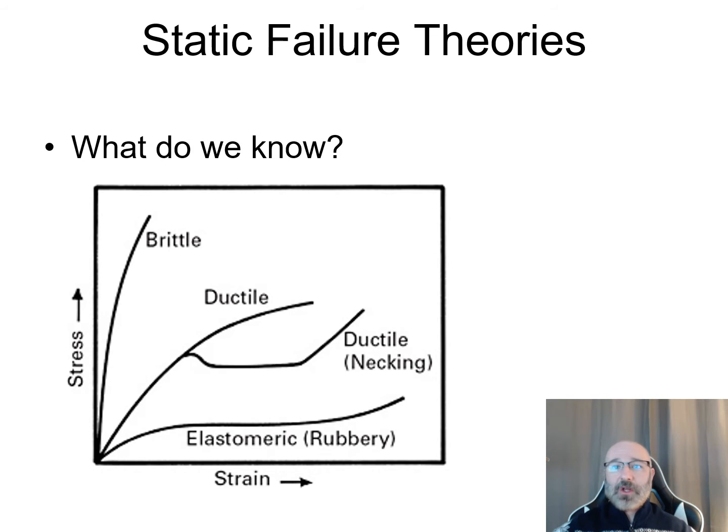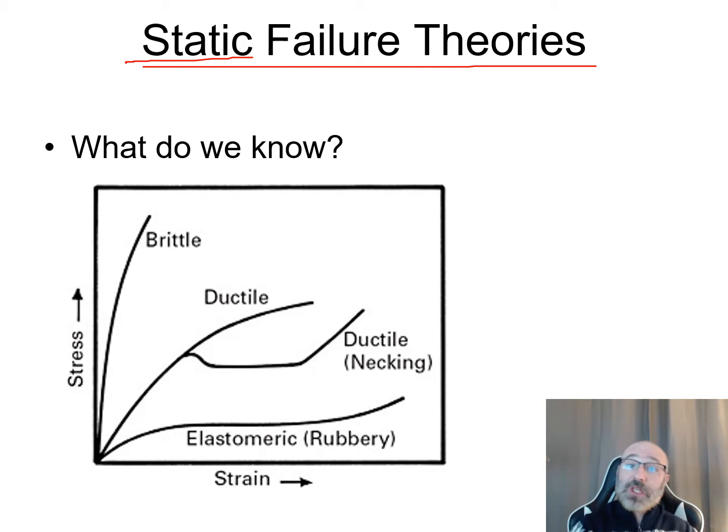So as we mentioned earlier, a lot of the loading we're dealing with within this module here and within this course right here for that matter is going to be dealing with our static loading right there. So with our static loading, let's take a look at some of the static failure theories. Now, a great resource for the static failure theories right here is our typical stress strain curve. We can get a lot of information from the stress strain curve right here. Now, whether this is something that's given to you from the manufacturer, and you have this information that you can take a look at for these different types of materials, or if this is something that you've developed from testing. So maybe it's a product, or just a sample, a dog bone specimen right there that you're looking at, and you want to take a look at the mechanical properties of it right there. Well, the stress strain curve is a great way to do that.